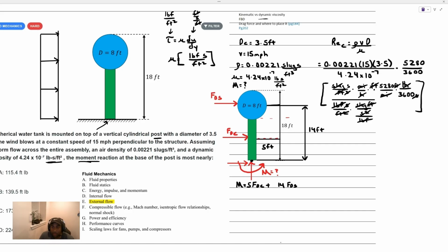Let's go ahead and note down what this is. 401,344, and it is dimensionless. That's an important value. We're going to use that in a chart a little bit later. What about the Reynolds number for the sphere? If we plug in quickly for the Reynolds number for that sphere, we have pretty much all the same terms, but the diameter value is going to change. This diameter was for the cylinder.